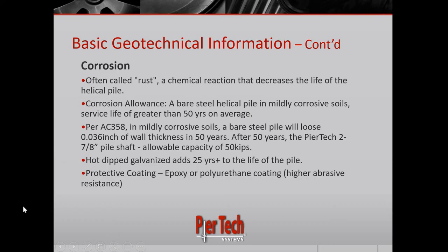Other protective coatings are out there. So let's say you're putting in a marine pile into a lake or near brackish water. There are epoxy coatings and polyurethane coatings that you can add onto the pile after the fact that have higher abrasive resistance when you're going into the ground. So they're able to stay on there a little bit better.